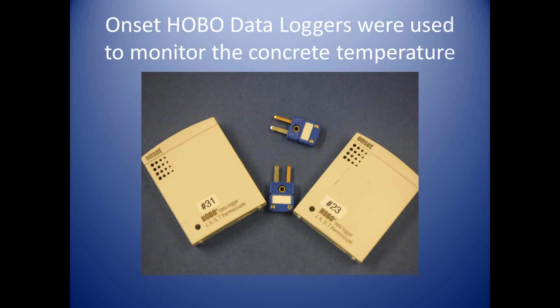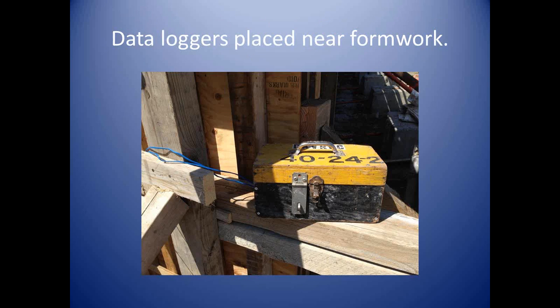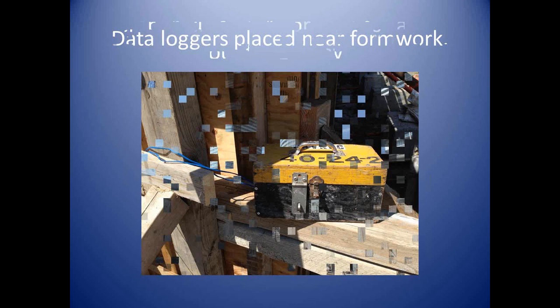Here's another shot of the wooden box where the data loggers were stored. And the data loggers were placed right next to the formwork. We drilled some holes in the formwork and brought the wires out. And the temperature monitoring was carried out for 10 days. And the readings were taken every hour.